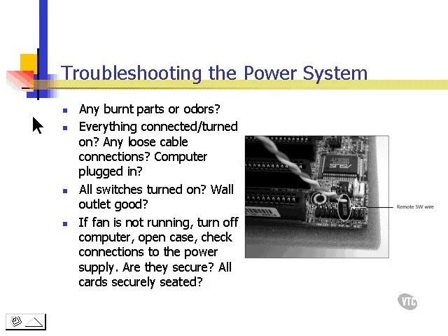We need to start asking some questions as to, are there any burnt parts or any odors that we're smelling? Is everything connected? Is there a loose cable or a connection? Is the computer plugged in? Are all the switches turned on? Is the wall outlet good? In other words, if we were to plug something else into that same outlet, would it work?